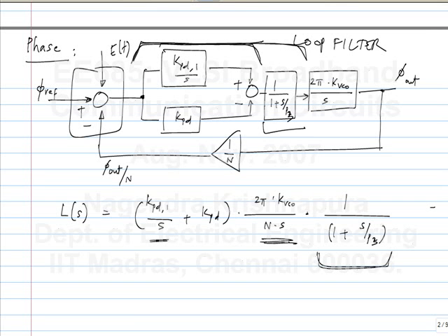So we made all these arrangements, like we've increased the lock range for sure by introducing an integral path, and we can further suppress the reference feed through using a third pole. But it looks like the reference feed through error itself has gone to 0 because of the different steady state conditions of this loop. So do we need this P3 ever?